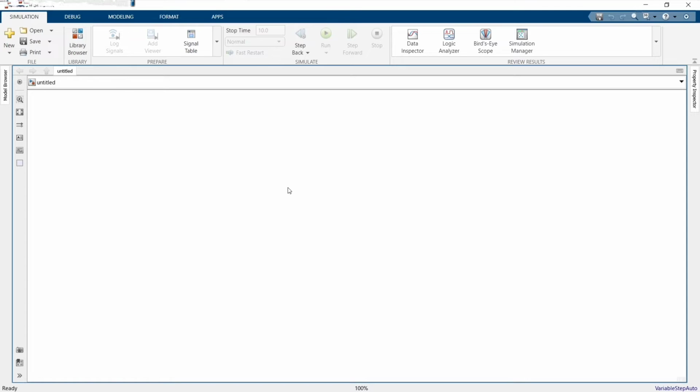Now I'll just change the location of my connection ports to right. This is the advantage of using a connection port. You can specify the location, or else outputs and inputs can be used, but location specification is not allowed. Let me connect my out to in and out to ground. Now I'll rename the subsystem to my EMI filter. So my EMI filter is done. My source cutoff is also done.